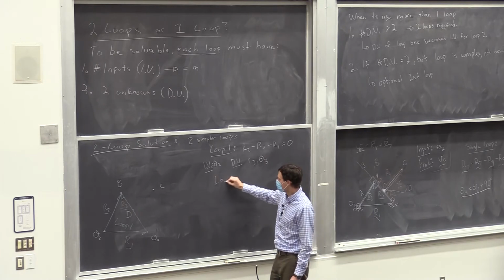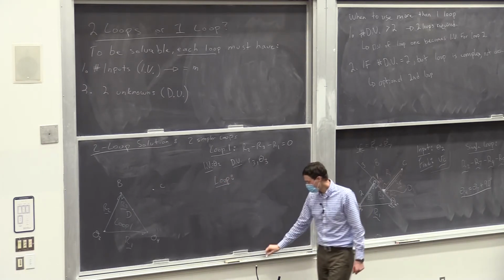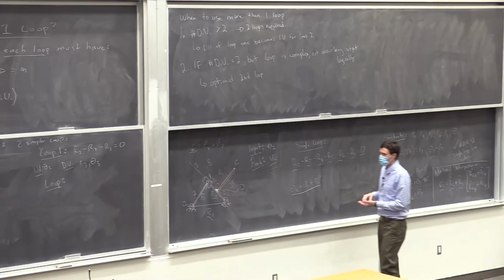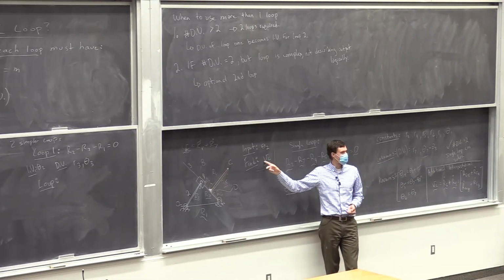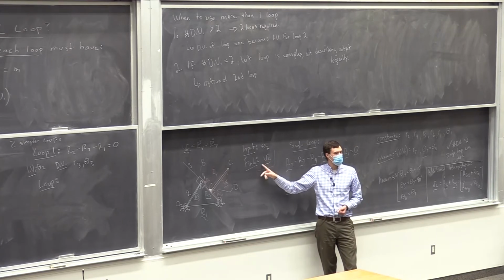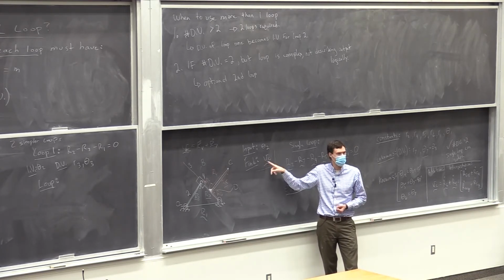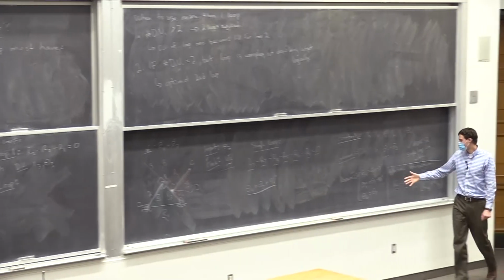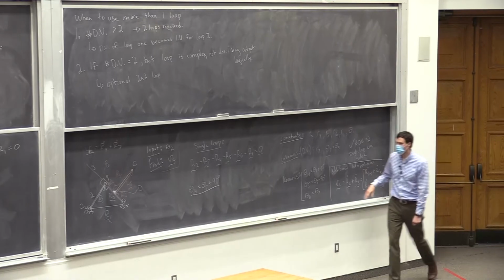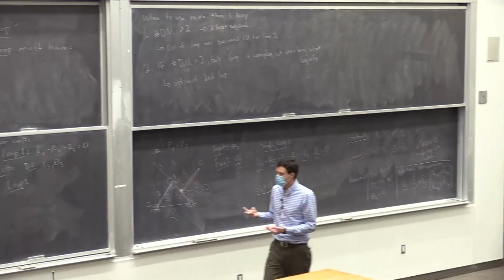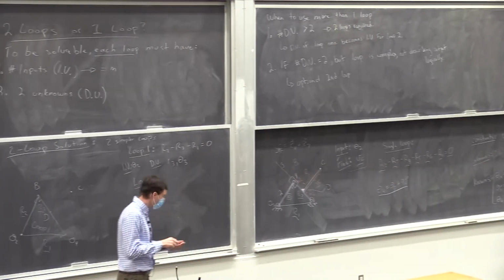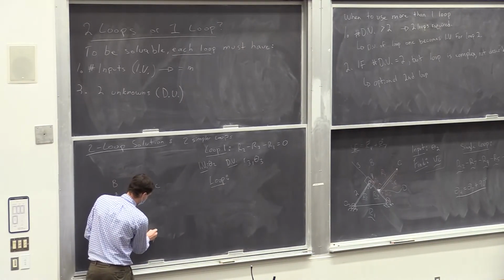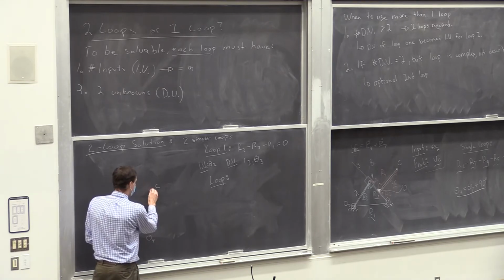Now we're going to add our second loop. And this time, rather than just putting a bunch of vectors on, my big suggestion to you on loop design is think about what your solution looks like and design vectors that give you your solution directly. That can simplify your problem a little bit and eliminate this last step of having an additional equation afterwards. So I'm going to design 2 vectors that give us the position of C relative to a base point, like O4. So let's just give X and Y position of C.